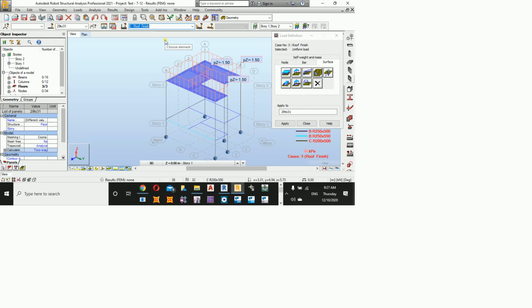Okay. Now let us say that we have finished the slabs. Although there are other loads, I don't want to spend a lot of time on each and every load. But now the second thing is going to be the wall, because the concept is different. AC, water tank, all of them are going to come on a slab, so they are going to have the same concept of live and dead load, but walls are line loads. So we need to see how to do it.